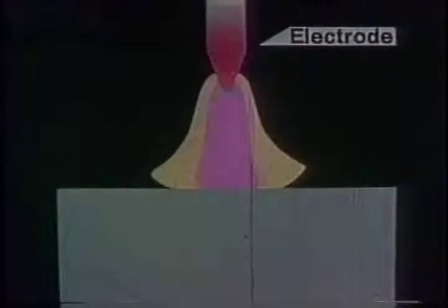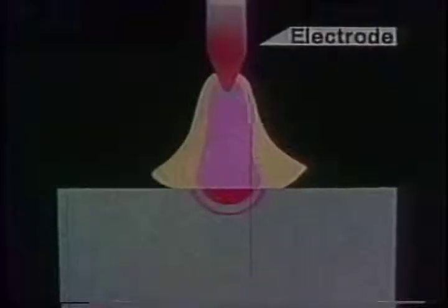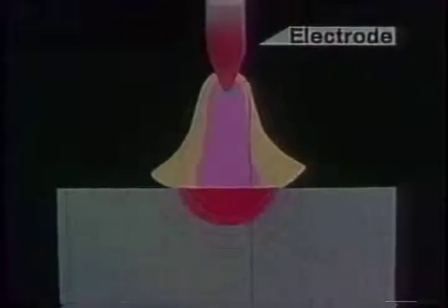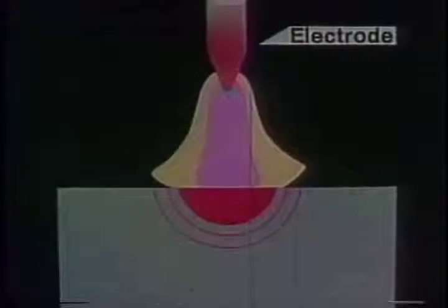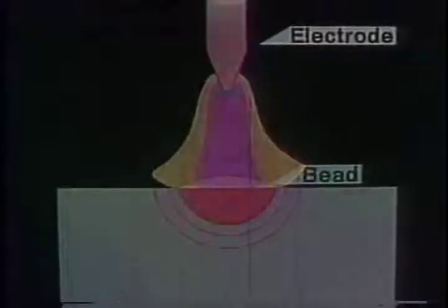Penetration mechanism. Now let's proceed to the penetration process. For a low energy density heat source like an arc, the input heat is almost radially transferred in a workpiece, and the region above the melting point forms a molten pool, where the heat is mainly transported by conduction and convection. As the energy density is low in an arc, loss due to vaporization on the surface is negligible. Thus, the bead configuration is wide and shallow, as seen in this figure.